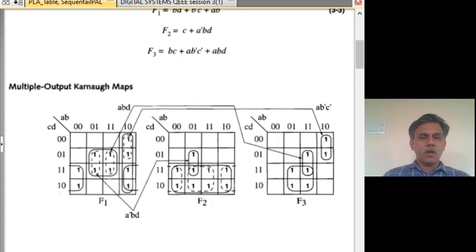So now you look at the K-map for f1, f2, f3. Normally we would have minimized f1 by looking at this K-map and looking for the largest coverages. In particular, we will be looking at the prime implicants, and we will only include prime implicants and not just implicants, which means that here this is one 4 square and this is another 4 square, the whole horizontal vertical one, and this followed by this 3 are the ones which we would have included.